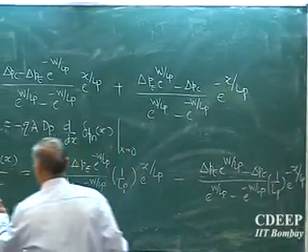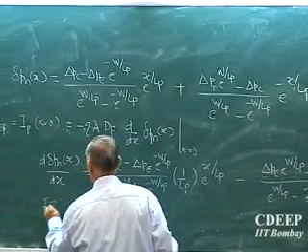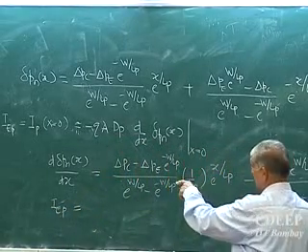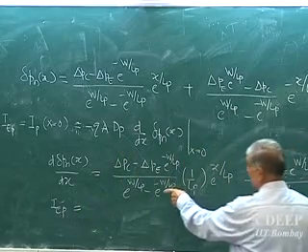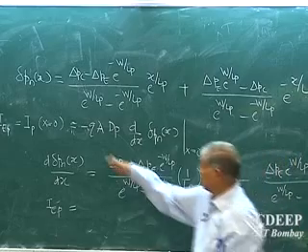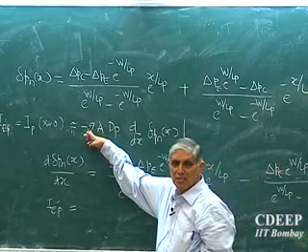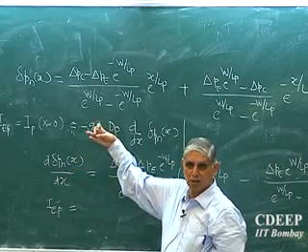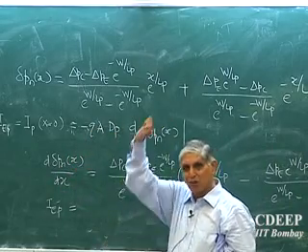So first do emitter current, IEP. Please remember, this is minus, this is plus, but there is a minus sign there. Why has this minus appeared? This is how we define the hole current going across the gradient: current goes opposite of that.